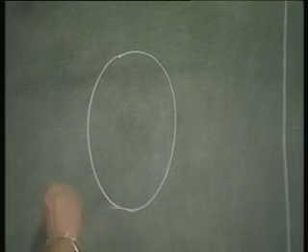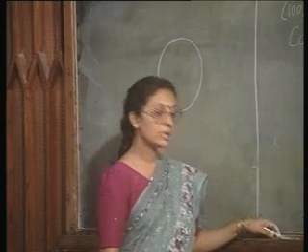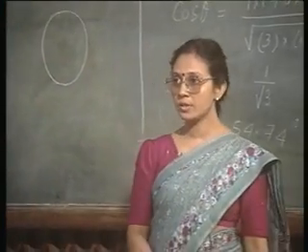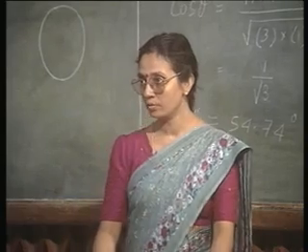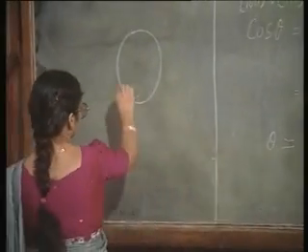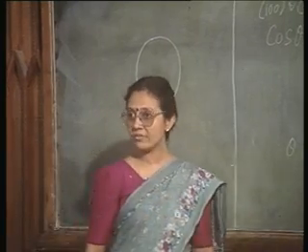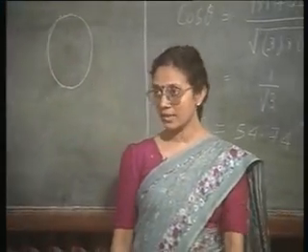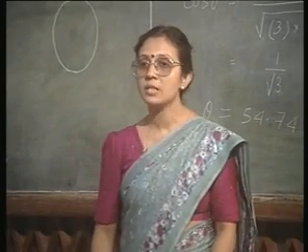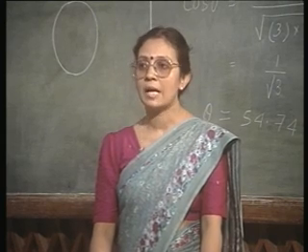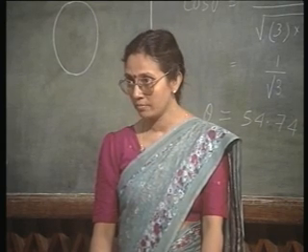Big disc of silicon. I would like to cut pieces from here. How does one cut? Usually what is done is you scribe using a diamond tipped tool. You scribe like that and then you try to cleave it, break it along the scribe lines. So, the natural tendency of silicon will be to break along its natural cleavage plane.